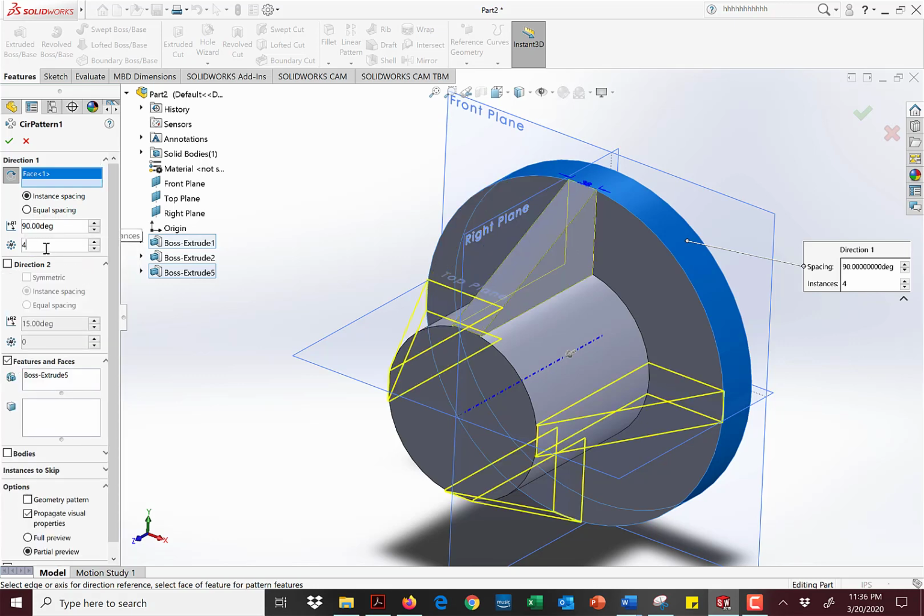Now, people ask me the question, well, why would I use instance spacing? Why not just use 360? Well, I came out of an industry where we designed product that had to be installed only a certain way, but they happened to be round. We didn't want to baffle people, but we were making something called baffles, so there was a little humor in there. In order to make sure someone installed it correctly, we actually had to offset the bolt holes, and one or the whole family would be clocked a certain way so that it was keyed how it would assemble. That is the reason why instance spacing exists.